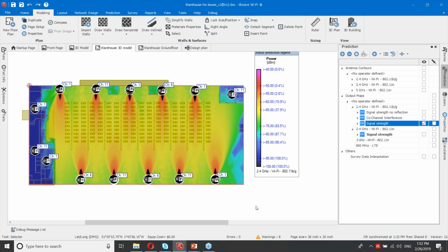Okay, can you explain the power levels choice for 2.4 and 5 gigahertz? So why are they different, right? They're different because the propagation characteristics are different. It is a little over double in frequency, and what it means is 6 dB in propagation. So there is a 6 dB path loss differential just because of frequency.